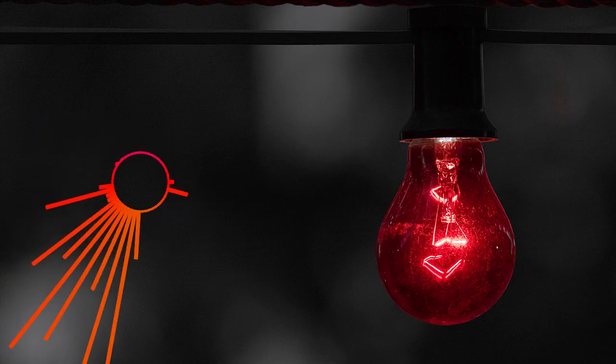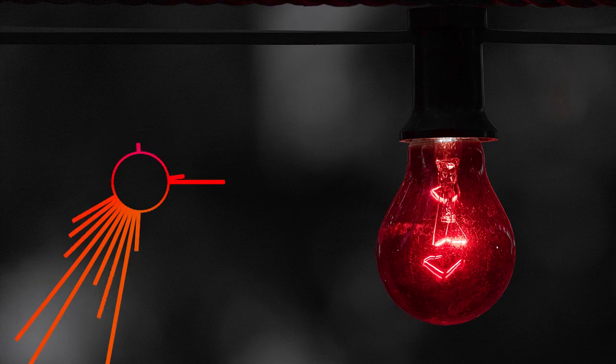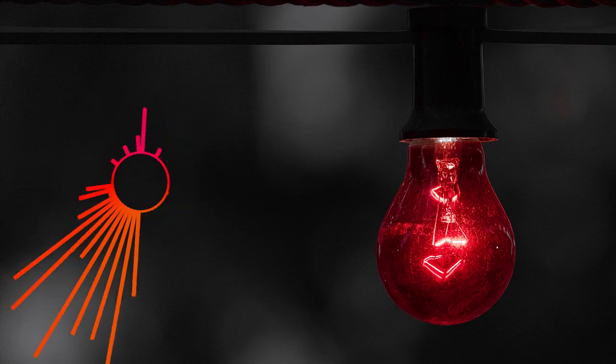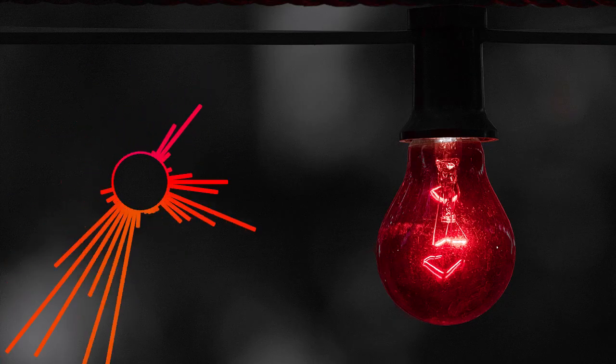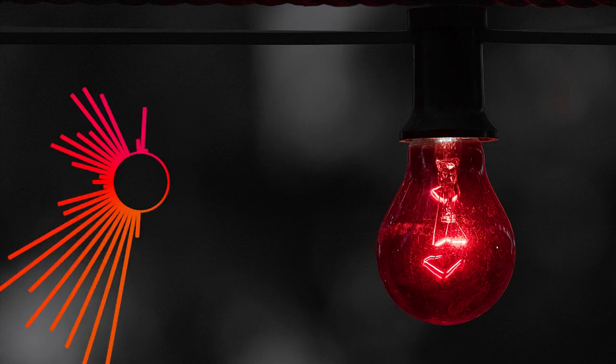Let's summarize the most important takeaways from this lesson. Incandescent and halogen use a glowing filament, produce heat, and no ballast is required. Fluorescents use gas and phosphor coating, are more efficient, and need a ballast. HID is very bright, used outdoors, uses gas at high pressure, and needs a ballast. LED uses a chip and a circuit board, is super efficient, and needs a driver, not a ballast.